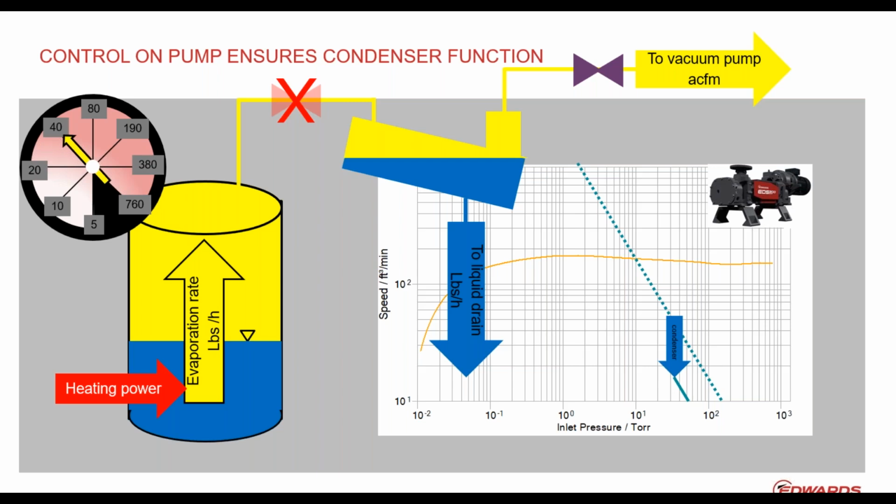And then again, use this condenser in the very first phase of your reaction, where all the vapor is coming off, where your drying goods are really wet and you only want to dry the liquid agent out in that wet phase, or in a batch distillation, just get rid of this light boiling fraction as fast as you can. Your condenser is your best friend.